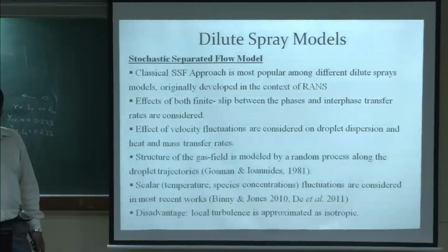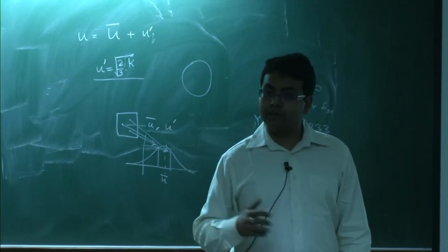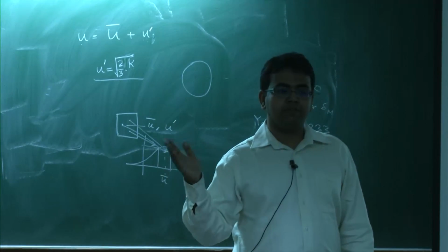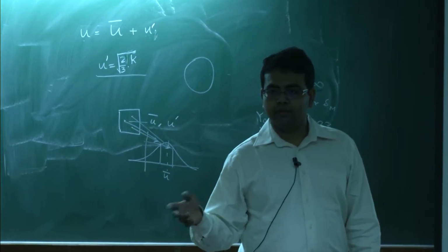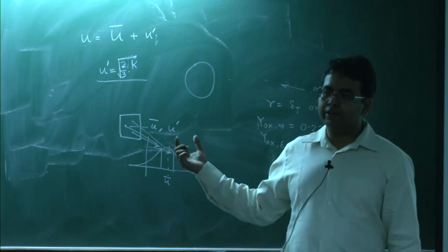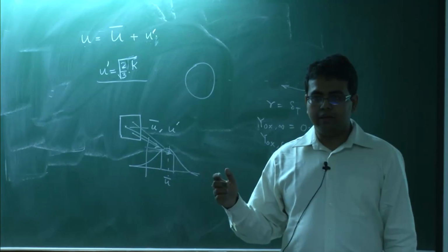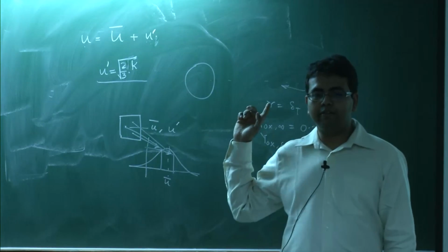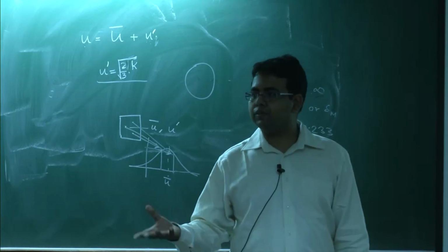As we know, in a turbulent flame, you have seen a lot of demonstrations by Professor Poinsot, the temperature and the species mass fractions vary wildly with turbulence. So it is logical that your model should also include the effect of the fluctuating temperature and concentrations, because we have seen that the evaporation rate depends on the Spalding number, which is a function of temperature and species concentrations.